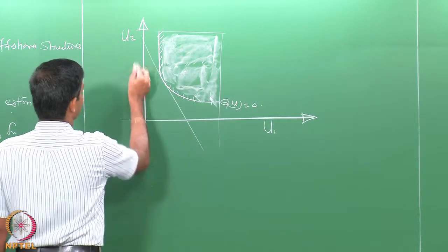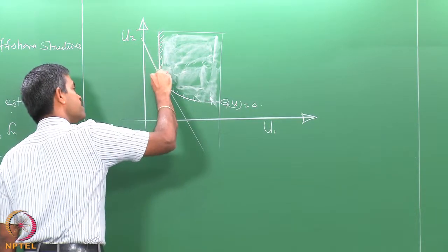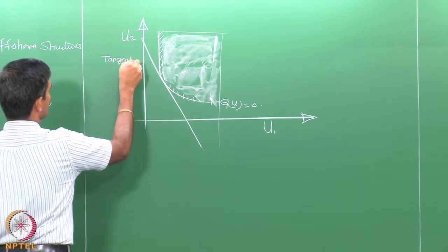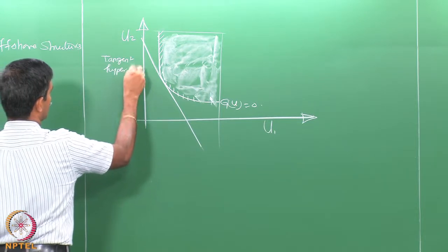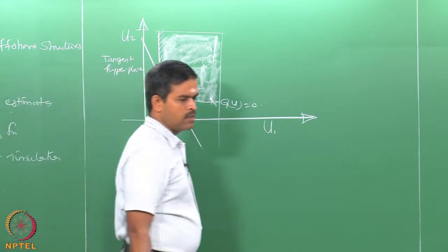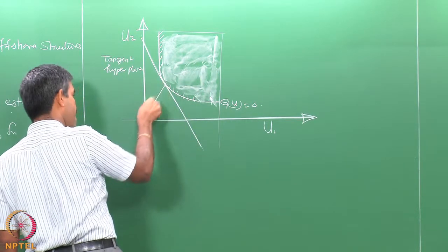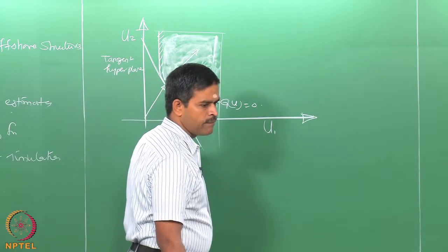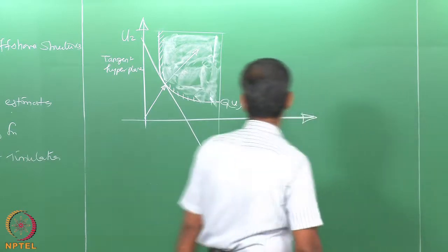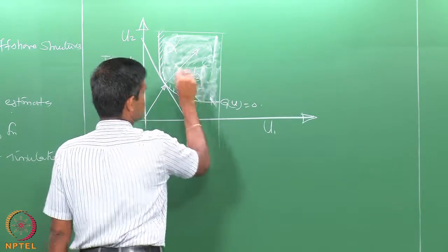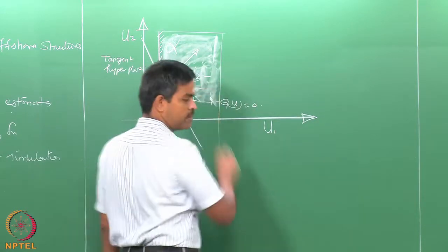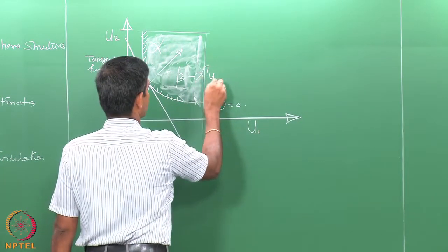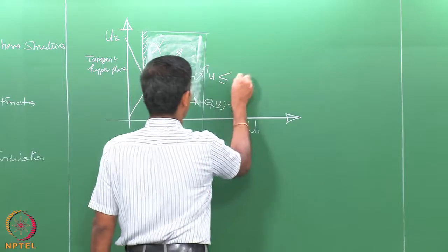I draw a tangent hyperplane to select the design point. So, this helps me now to locate the design point, which can be the region of alpha, and of course, the value beta minus alpha transpose u should be less than or equal to 0.